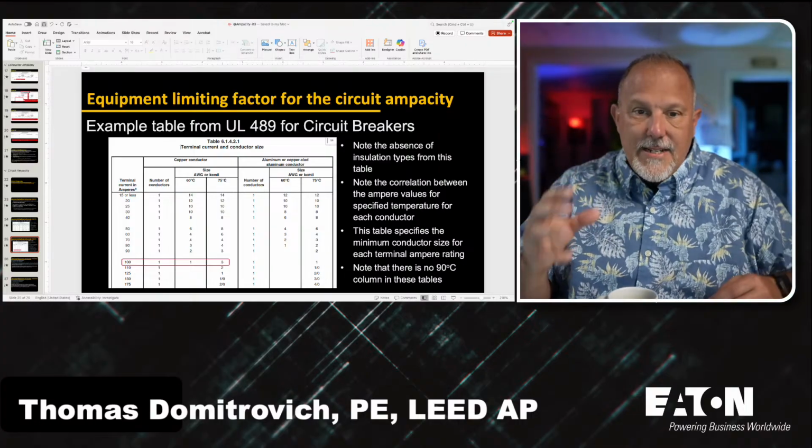So basically what happens when I deal with equipment, the size of the conductor and the amount of current that I'm pulling through that conductor will generate heat. And I will test my equipment with a specific size conductor, meaning I can get larger, but I can't get smaller. And I can only pull so much current over that conductor, based upon either the 75 or 60 degrees C column, however the breaker or equipment is marked.